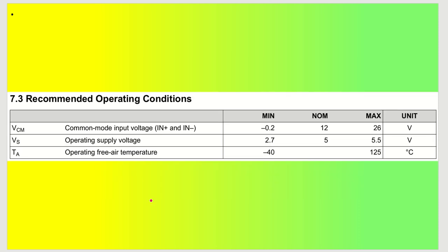Let us talk about the recommended operating conditions. In the recommended operating conditions, we have a nominal supply voltage of 12 volt, as I was mentioning. You can even utilize it for a 15 volt application, as generally 15 volt is the supply for IPMs or something like that. So there also you can utilize this, or even 24 volt applications you can go ahead and utilize.